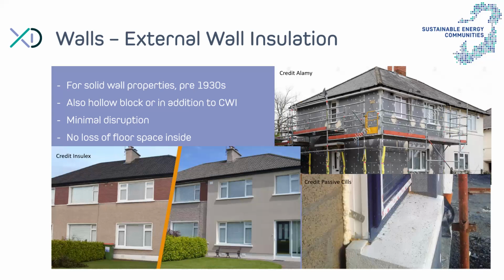The downside of it is that it's quite expensive. It's a significant budget for an average house. And the other aspect is it needs to be done carefully. The detailing needs to be good. So there's no point pushing this lovely insulation layer and then having your concrete sills, for example, jutting out, or a canopy over an entrance door, and all these kind of sticky concrete elements would act as cold junctions and kind of weaken the insulation layer. So all these, let's say, key junctions need to be detailed properly, and a lot of attention to detail, in fact, needs to be given.